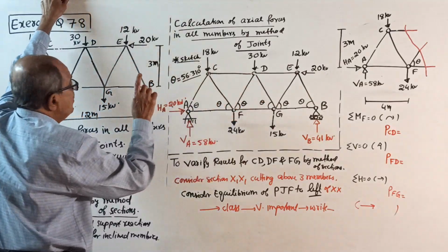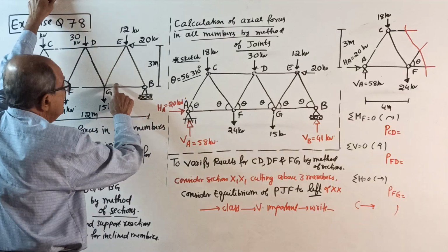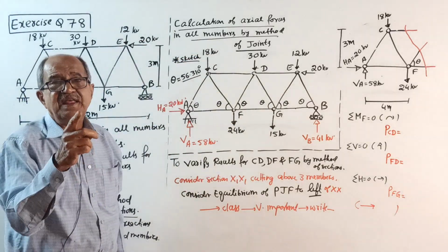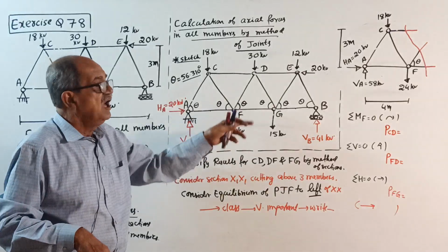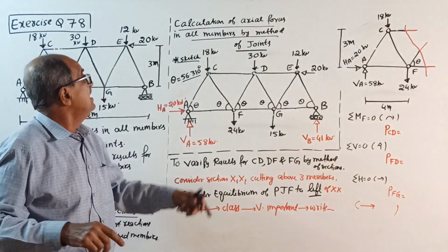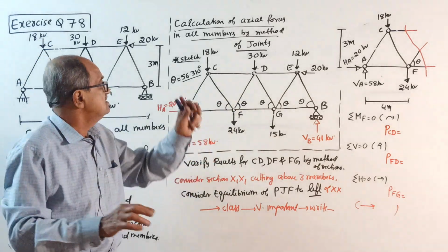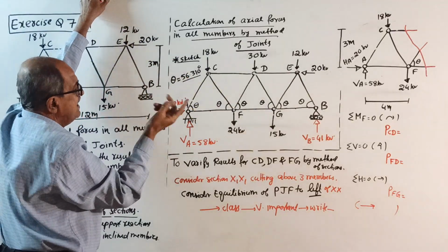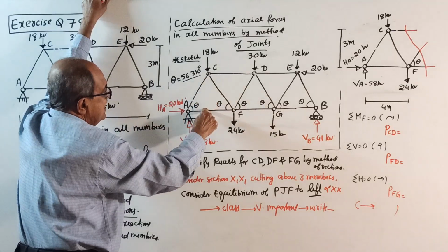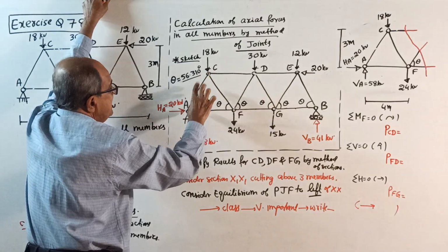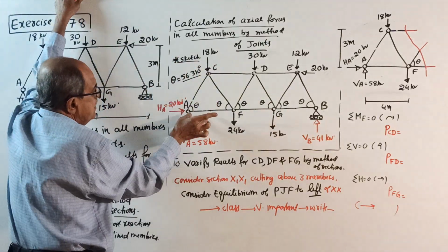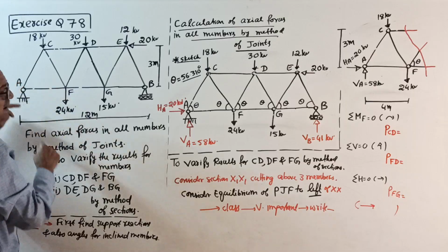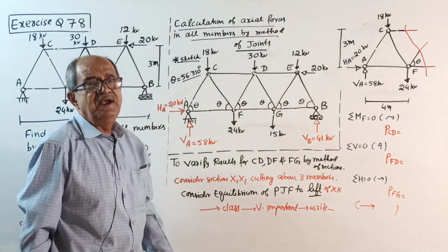Then, we want the angle for all inclined members. See, all are the same angles. Actually, somewhere here, in the sketch for finding reactions, there you show all this calculation. How I solved systematically earlier, that way. Exercise question means direct answer. So, take the angle theta, not here, in an earlier sketch, in between one sketch is there for finding reactions, theta, see. If you see a triangle here, see this triangle, tan theta equals 3 divided by 2. You can see very easily, tan theta equals 3 divided by 2, theta will come 56.310 degrees.